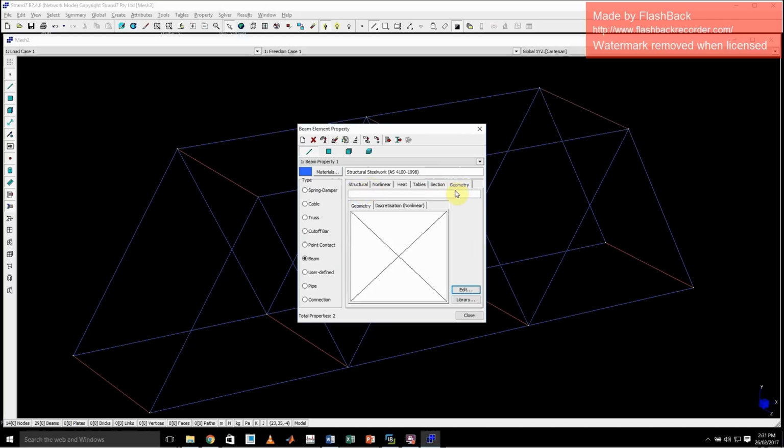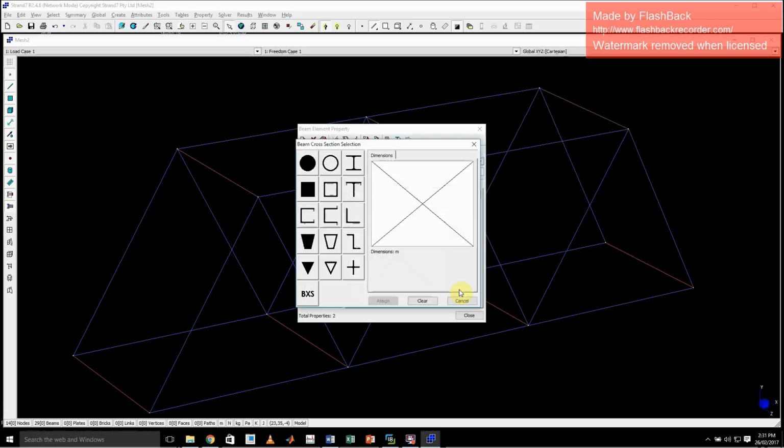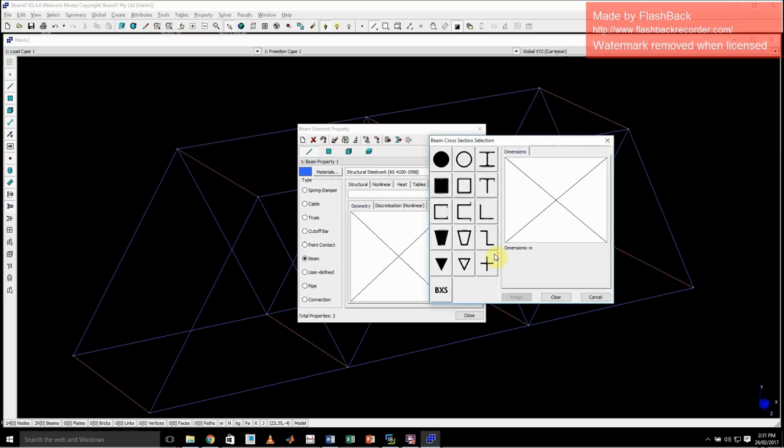We also need to always give our system geometry. Come in and pick whatever cross section it is that you have. If you are buying common materials, they are almost certainly going to be solid round bar, solid square bar, or RHS. They're by far the most common, but if you know a little bit more about how your loadings are going to work, you might be able to use things like I-beams and C-sections in order to make stronger, lighter structures. But make sure you pick some geometry, you give it some dimensions.